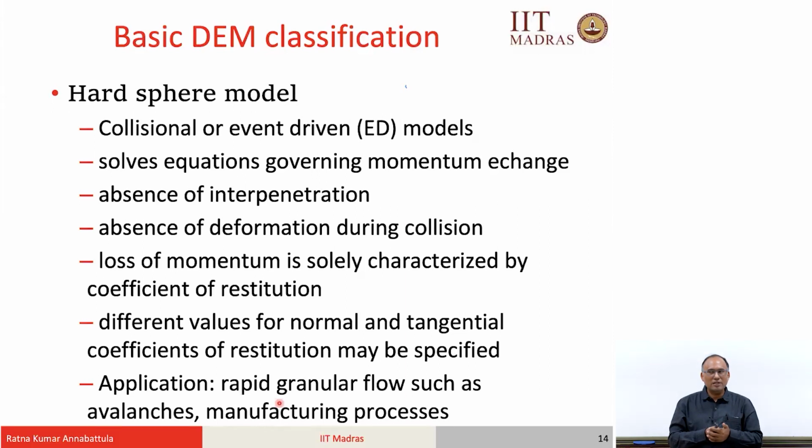property, right. You should know what materials you are simulating, and in the assembly if you have 2 or 3 different kinds of materials, you should know the coefficient of restitution between each class of materials, right. That is the energy dissipator. So, what it does is it simply solves momentum exchange, so sigma mv is equal to constant, right. That is what it does,